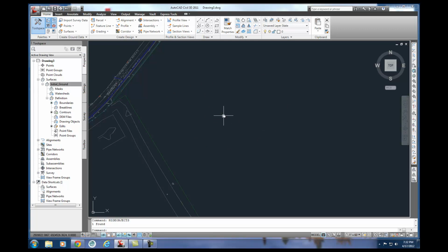First thing that you need to understand with Civil 3D is, you can draw a regular line in Civil 3D. There's no problem with that. But what Civil 3D really likes is what's called polylines. If you've never messed around with polylines before, they're in AutoCAD. But they have a little bit more data in them than a regular line, and each little part that you make of a polyline is not some completely separate segment. It's related to the other parts, and so polylines are real popular in this program. Whenever you draw something, remember that you want to make it a polyline.